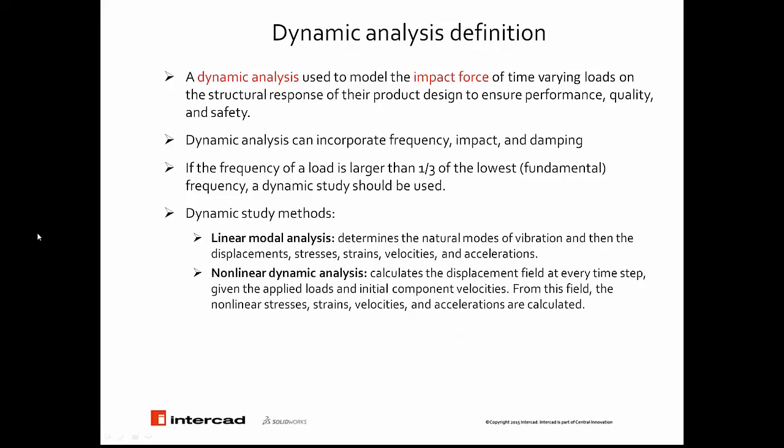We can incorporate frequency, impact, and dampening in this type of study. When we are using this, basically if we're running a frequency analysis and finding that the frequency of the load is larger than 1/3 of the lowest or fundamental frequency, the dynamic study needs to be taken. We have two different methods to take the dynamic study.